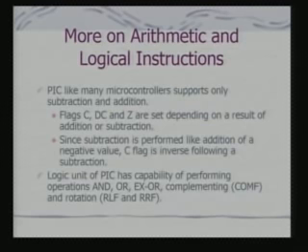Since subtraction is performed like addition of a negative value, the C flag behaves like a borrow flag when a subtraction operation is executed. The logic unit of PIC has the capability of performing operations like AND, XOR, complementing, as well as rotation, just like any other standard microprocessor or microcontroller.